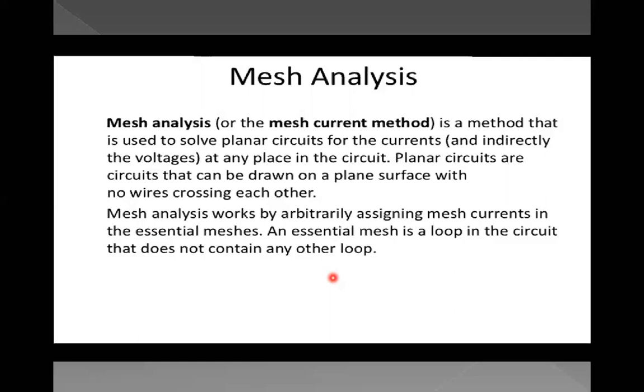Mesh analysis works by arbitrarily assigning mesh currents in the essential meshes. An essential mesh is a loop in the circuit that does not contain any other loop. There are certain steps for determining the mesh currents.